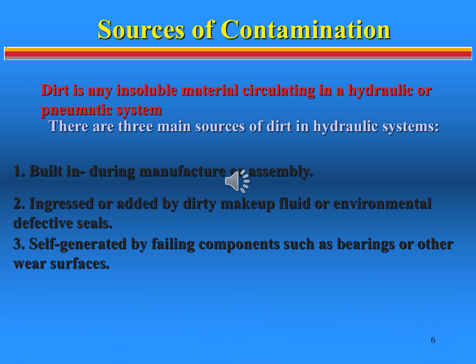During manufacture, contaminants such as weld slag, metal chips from drilling, as well as rust, paint chips, and greases may accumulate in the reservoir and be circulated through the system. It has been observed that the practice of some shops is to collect oil leaking from a machine and reuse it. Exposed to the atmosphere, oil absorbs numerous types of contaminants and therefore should not be reused.